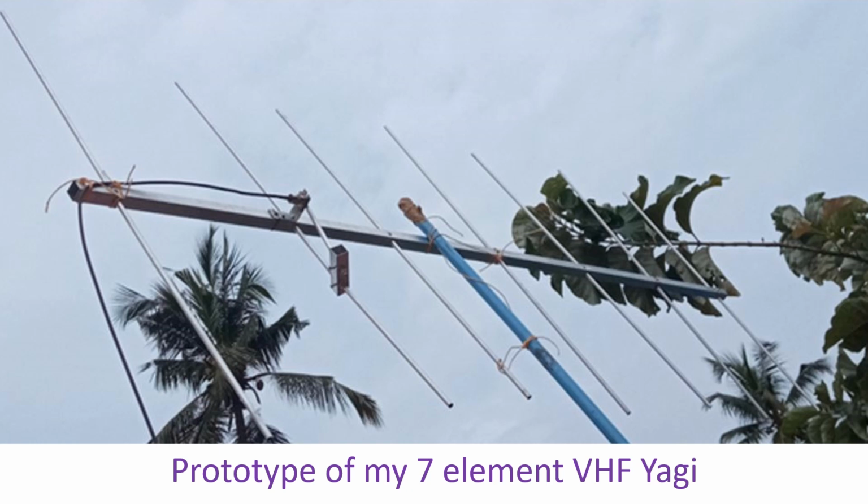When I tested my 7-element Yagi-Uda antenna for VHF, when I turned the antenna south in the direction of VU2 MJJ repeater, access to VU2 EDJ repeater in the north was completely lost. My vertical omnidirectional antenna gives access to both repeaters.